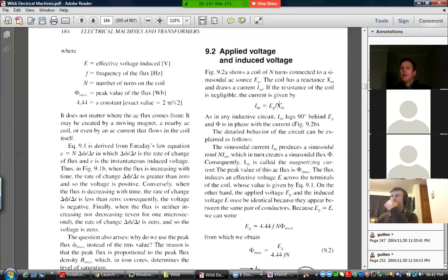But assuming that it is negligible resistance, then our impedance, Z equals R plus jX. If the R term is small, then we can just focus on the X term. And this formula is just looking at magnitude. So I'm not looking at the phase shift, just looking at magnitude here. Basically, we're just saying that's equivalent to Ohm's law, V equals IR. But we're not dealing with R, we're dealing with Z. But not all of Z, we're dealing with a subset of Z. The R happens to be 0, and the X component is all that matters.